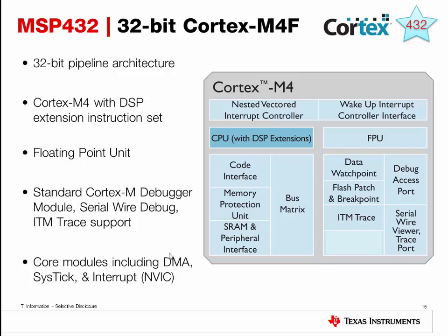So in this particular Cortex-M4F flavor that was chosen by MSP432, the device also includes a Nested Vector Interrupt Controller, or NVIC. It also includes an FPU, floating point unit, as well as the enhanced DSP instruction set that comes with Cortex-M4. From the debugger standpoint, it features a standardized Cortex-M debugger module, serial wire debug, as well as ITM trace support. Since this is a Cortex-M4F core, it also inherits a number of peripherals that come from the Cortex and ARM family, including the microDMA, SysTick, as well as the interrupt controller, as mentioned before.